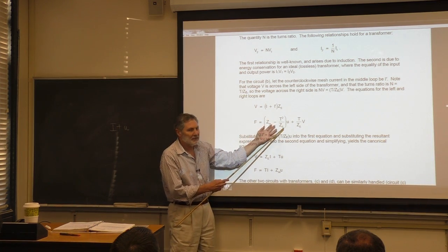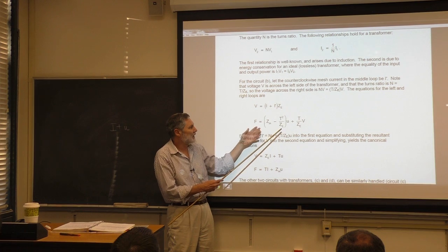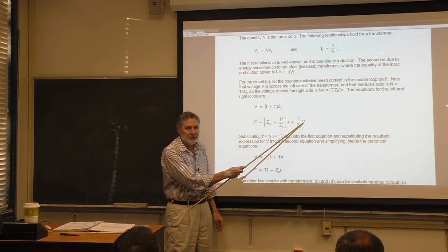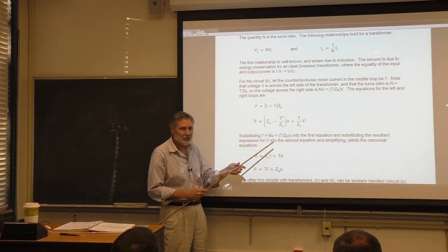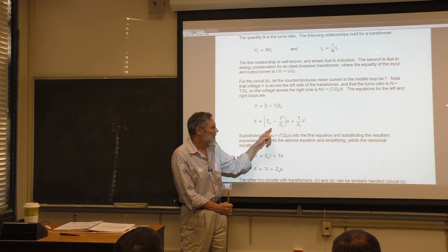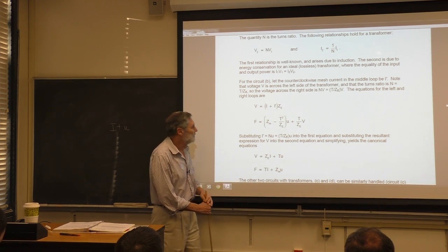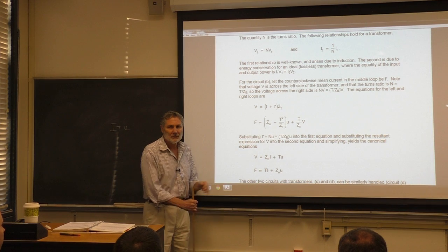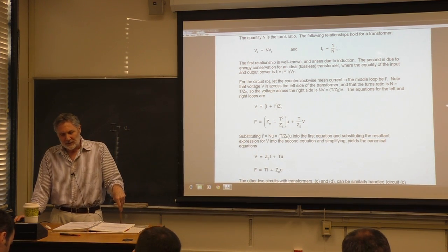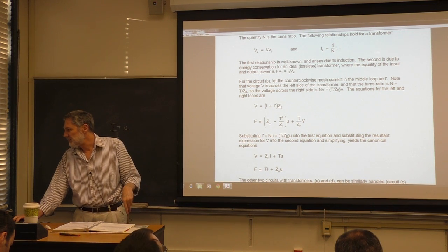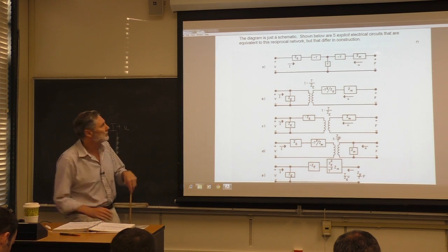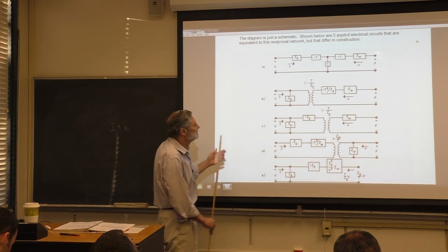Well, we don't have our independent variables of I and U. We just take this expression that we just got, the first canonical equation, substitute it into here. So we're headed towards the canonical form, right, where the only variables on the right side are U and I. And when you do that, you get this. So that proves that the first of the 5 circuits here, the first with a transformer, is equivalent to the canonical equivalent. This one, that would be B right here.